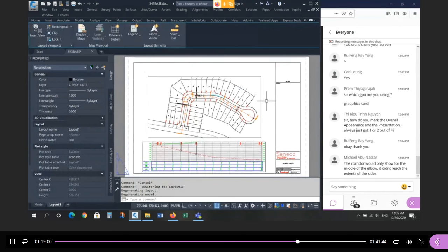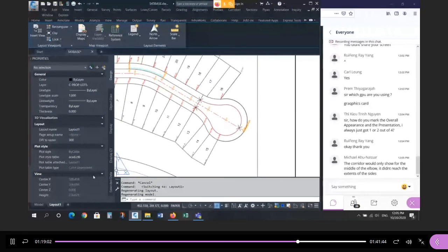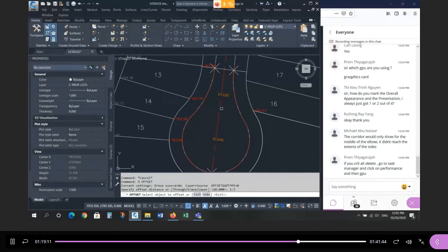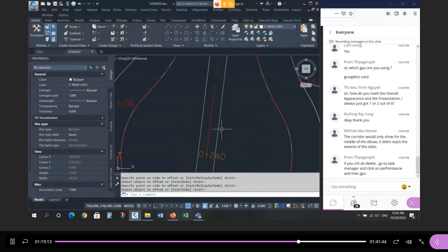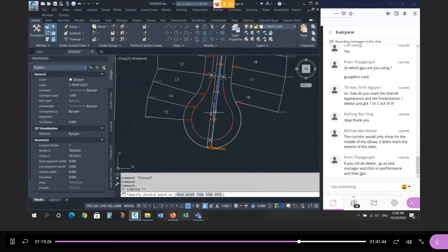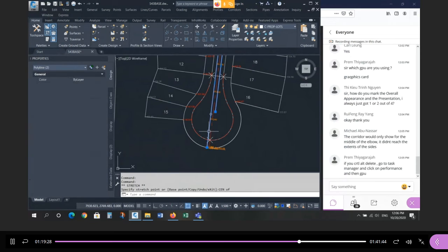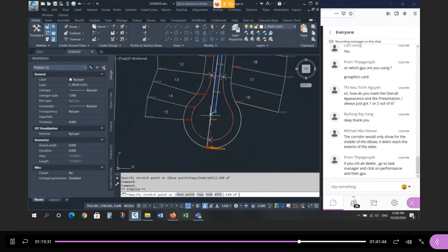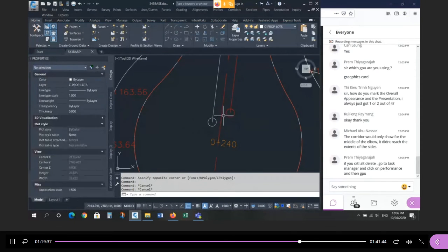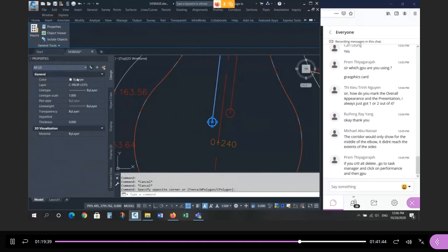If you go to the layout, the legend, when you're drawing your sewers, right? So if I suggest something here, if I offset by 1.5, offset 1.5, and I draw a circle of 0.75 and 0.75. If that's the size, then you want to have the same size in the legend, right? So if that's what it looks like, let me just color code these. I think this was the sanitary, this was the storm on my drawing. I can't remember. Just as an example.